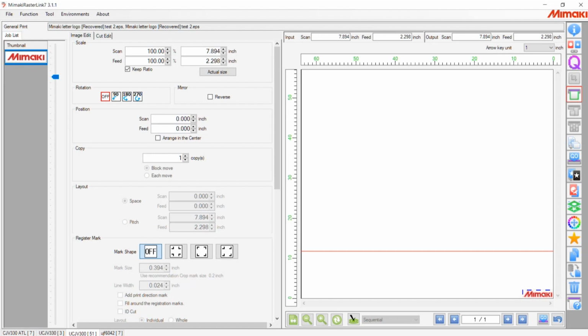All printing is intended to be printed on a white media. That's how color profiles are made. That's how it knows the white point of the media gives it that undertone, essentially. When you print onto something that's not white, whatever that color is takes on the undertone of the color you print on top of it, because all UV ink is slightly translucent, aside from our opaque white. But all other UV ink is, so your C, your Y, your M, and your K, and obviously clear ink, is going to be translucent.